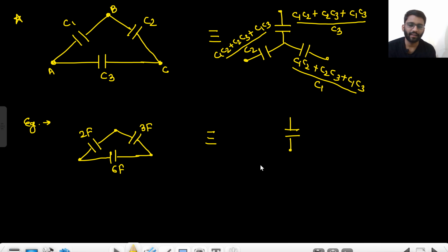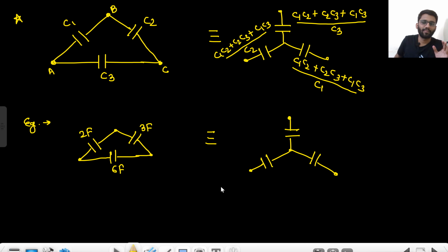Okay, for the previous two I have derived it already, so you can also derive it, but no need to derive as well. You have to remember these things. Only a few things I will tell you to remember, and this is one of them. And if you can't remember all these, at least try to remember the similar one when they are connecting Z and Z. So what will be the value? Z by 3, Z by 6, Z by 6. In case of capacitor, it will be 3Z, 3Z, 3Z. So at least remember that.